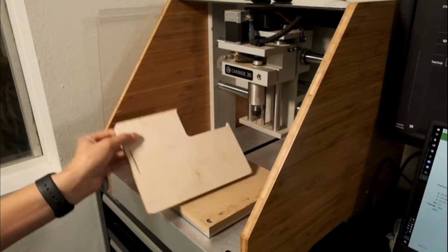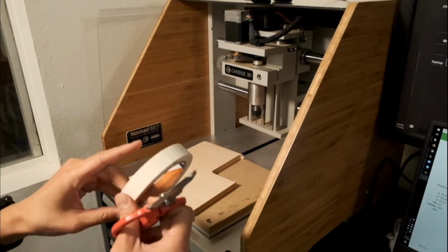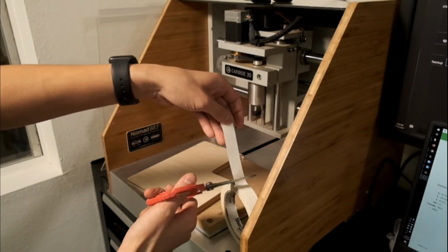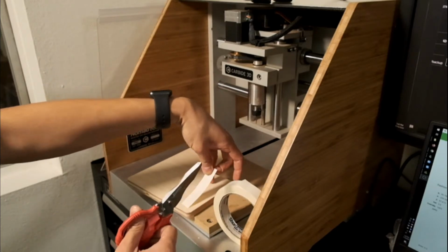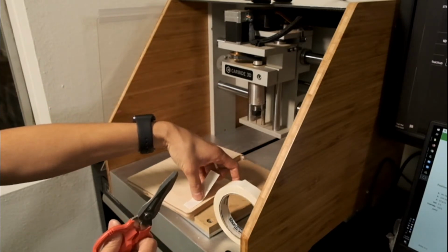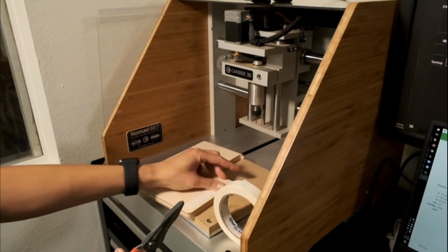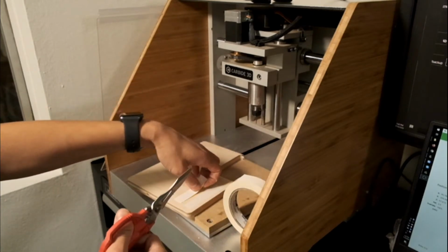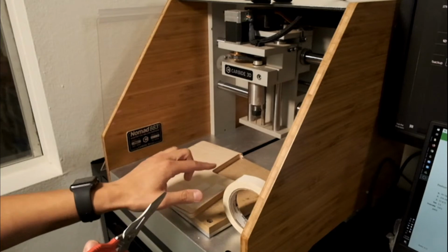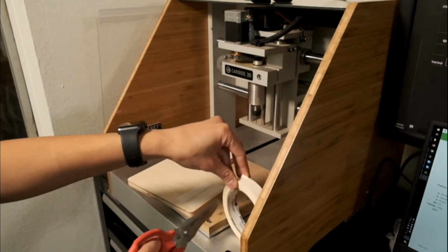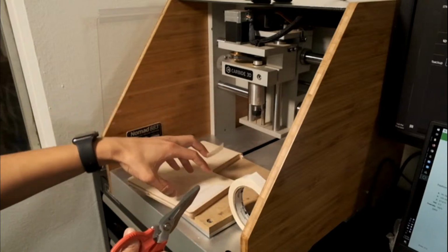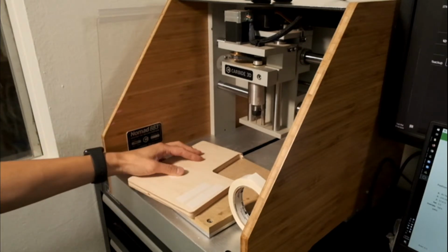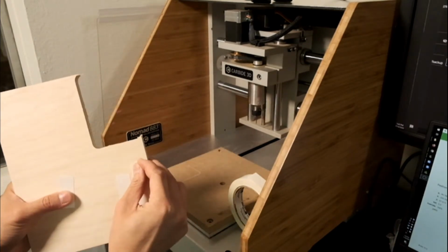Now I want to cut on this side, so I got to remember that I got to put tape on this side. How much double-sided tape you use is kind of subjective, but over time, after a couple mistakes, you'll figure out how much you actually need. So for something small and simple like this, I think about 3 square inches is roughly enough. If you want to be smart about this, you should also put a piece of tape somewhere out here, just because once your part gets liberated from your stock, the stock is also liable to go flying off somewhere. So it's always good practice to put some tape on both sides.